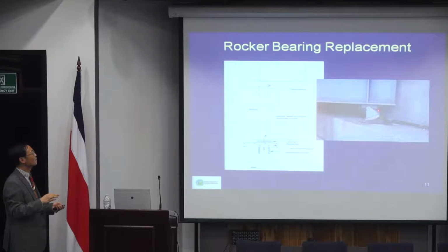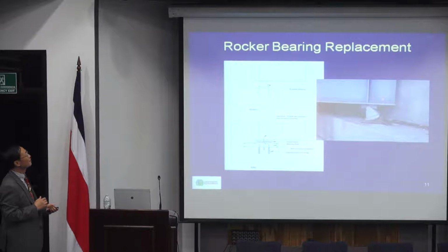Once it's more than 30 degrees, it becomes unstable, so that may collapse. Again, if you have these kinds of bearings, you may have to have constraints, or you may simply replace the bearings. And if you have sufficient support length, then you only need to replace bearings. And if you don't have this, you can just provide cables to tie it down to prevent it moving.